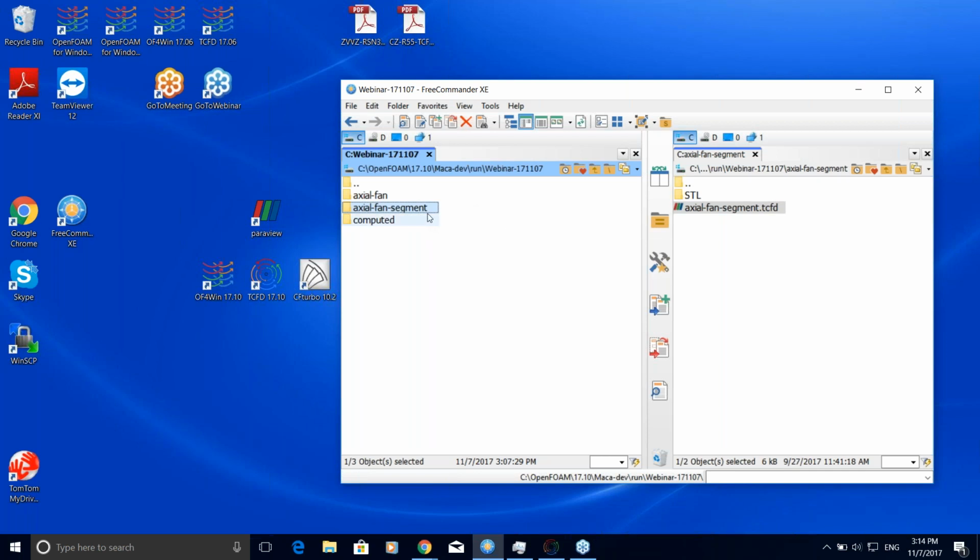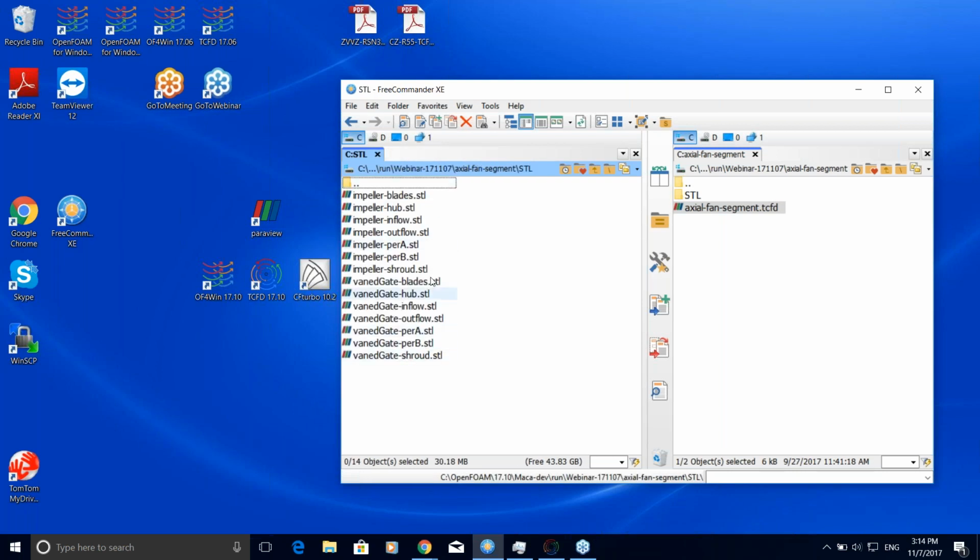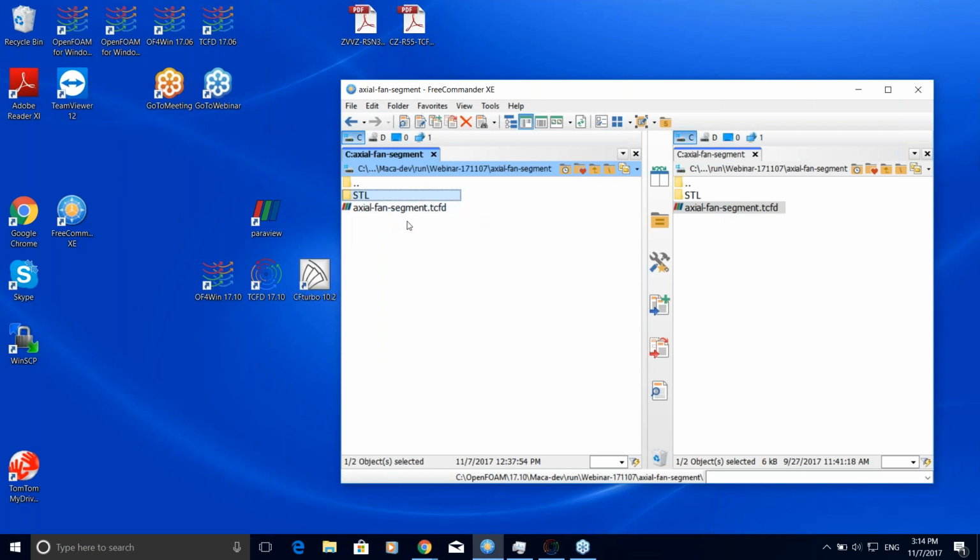to get the results for the axial fan. So from the export, what you need at the beginning is the input geometry. Our software provides both the STL geometry, so this is the usual export for almost any CAD software and design tools, and the configuration file, which is not compulsory, but you can preset the TCFD file, and then you can directly run the simulation without, let's say, any setup.